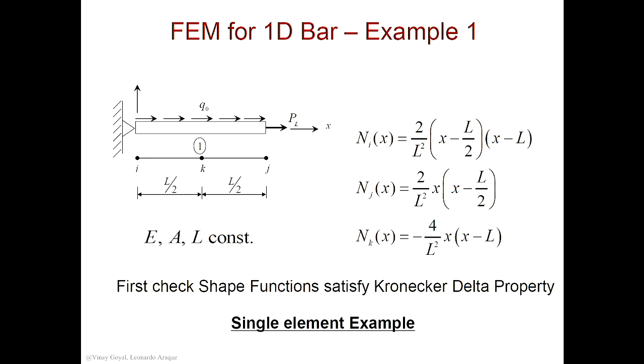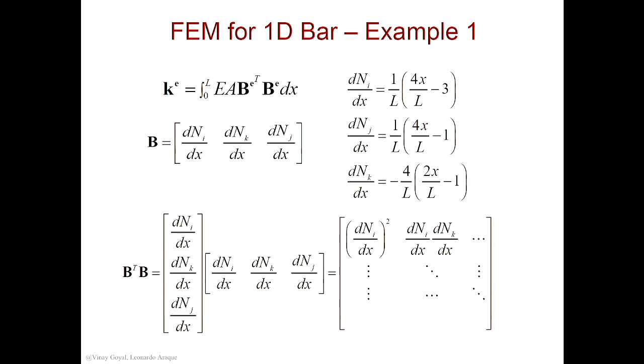These are the shape functions. If I select this to be 0 right here, this to be L half, and this to be L, you can derive this very quickly, and you will see that this works out very nicely. I just went into Mathematica and let it do the work. I calculated B, these matrices, that derivative, and the derivatives are given here.